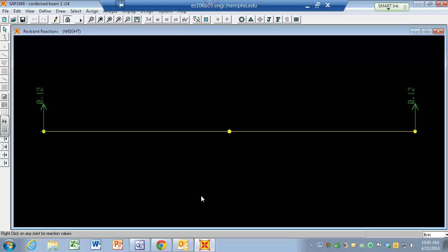And obviously, if it's that successful, you might be able to minimize it some. In this particular case, there's about, what is that? That's about a third. So you're looking at about 2 pound penalty for displacement. If you cut your displacement in half, which would save you about a pound, and you don't raise the weight more than a pound, there would be a better solution. So that's the idea of attempting to minimize the sum of the normalized weight and displacement. So that's how we would handle that problem.